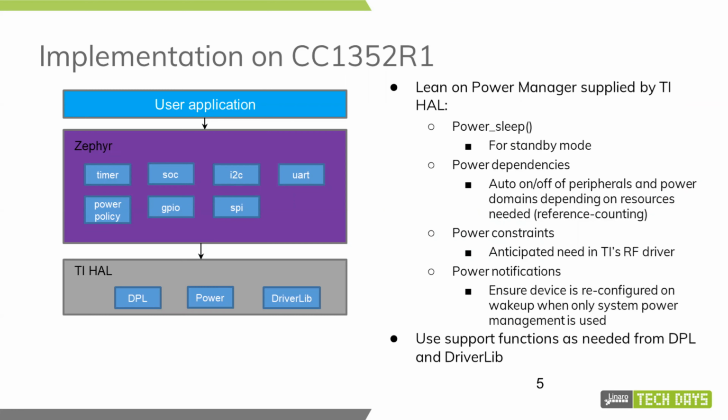And here's the implementation. The user application called is Zephyr. And then Zephyr has a bunch of drivers, the power policy, and SOC definition, where it knows how to initiate the various sleep and deep sleep states. And these would call into something called the TI hardware abstraction layer for support. And in this hardware abstraction layer, or HAL, there's a TI power manager that I leverage more substantially. And in there, there's a function called power sleep that I use for initiating the standby mode.